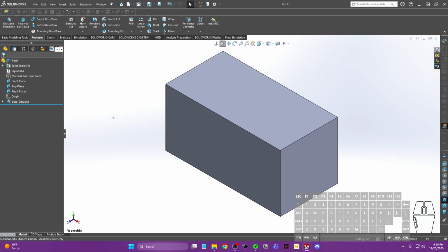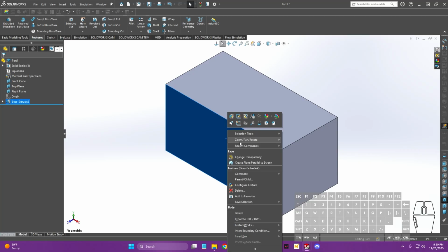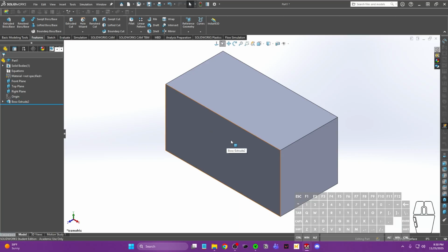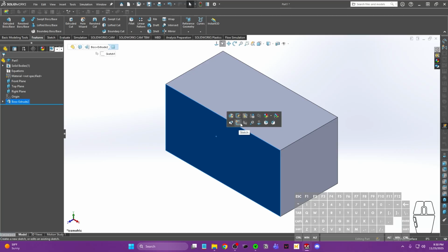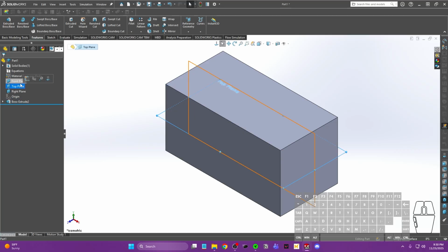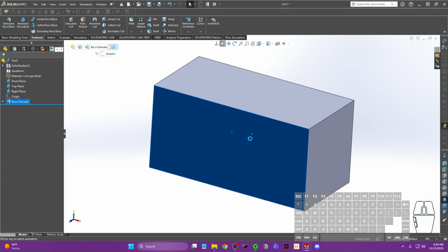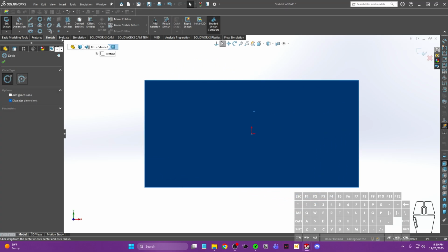From here, let's go ahead and do a couple of cuts from the object. I'm going to start the sketch on the left face here, or you could start it from one of the original axis planes. So starting on the left face, I'm going to go ahead and sketch, and I'm going to create 2 circular cuts. And you can see how I get started arbitrarily over here, or if I hover over where the center is, this centroid, it gives me this little line.